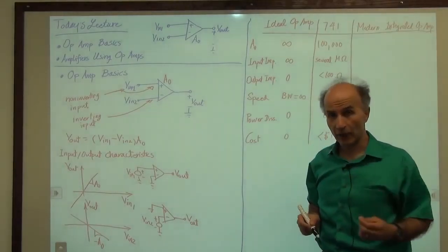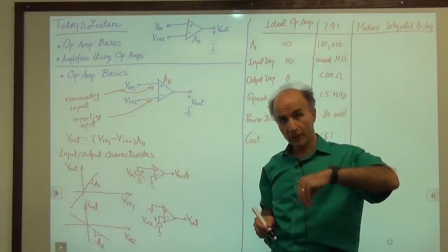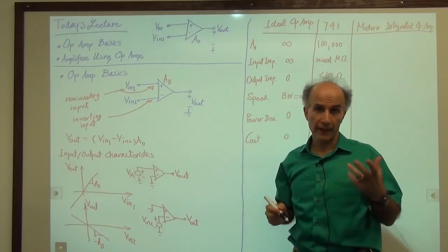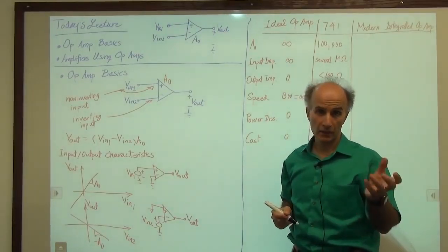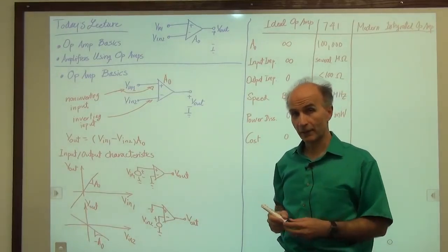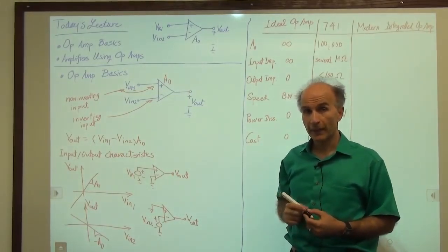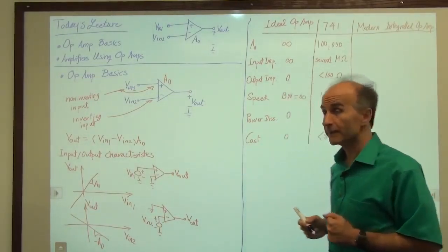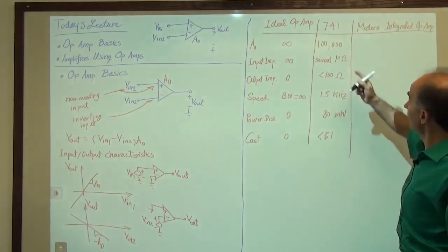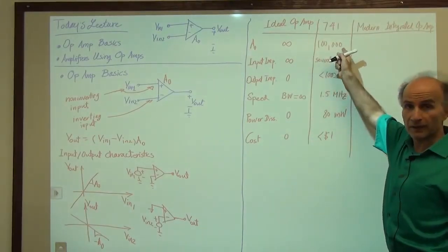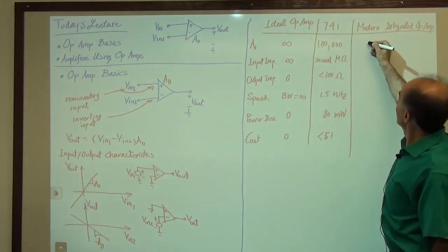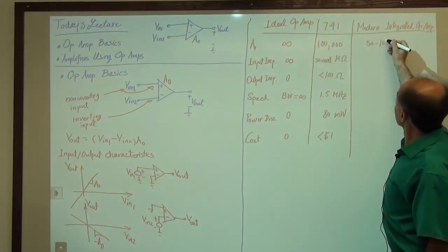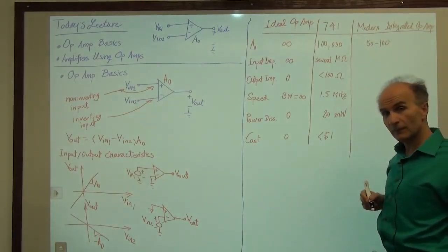They are not standalone op-amps. These are op-amps used inside the bigger systems. For example, inside a filter that you might have in your cell phone as you process the voice and data, etc. So for those op-amps, we have quite different characteristics. The gain is nowhere near this. So the gain these days is somewhere between 50 to 100, or even lower.